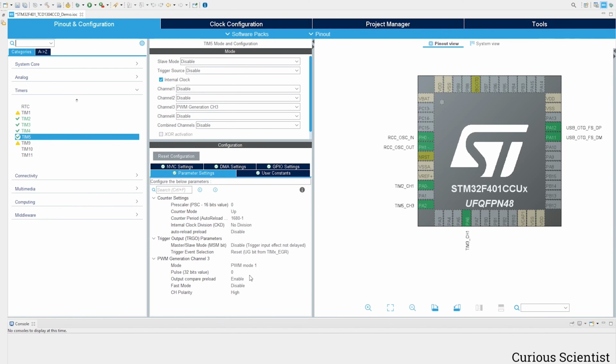And this comes with a certain duty cycle, and that is 336 minus 1. One very interesting thing is that actually this number will always be the same, whatever value you choose for the counter period, but this is how the duty cycle will change. So the longer the counter period is, so the higher or larger the number you enter here, the smaller the duty cycle will be.